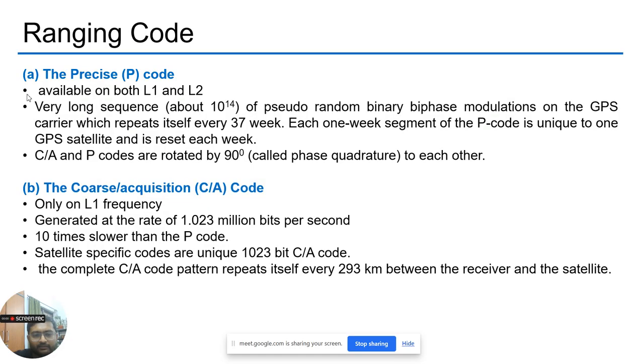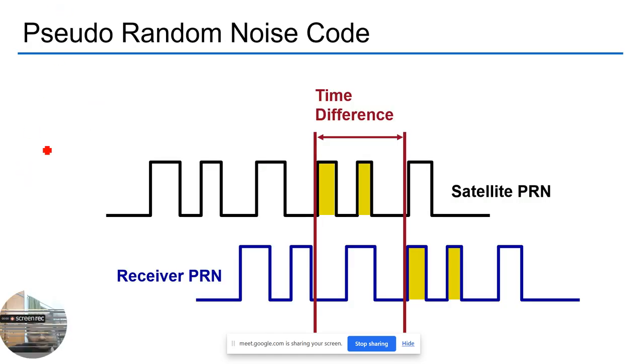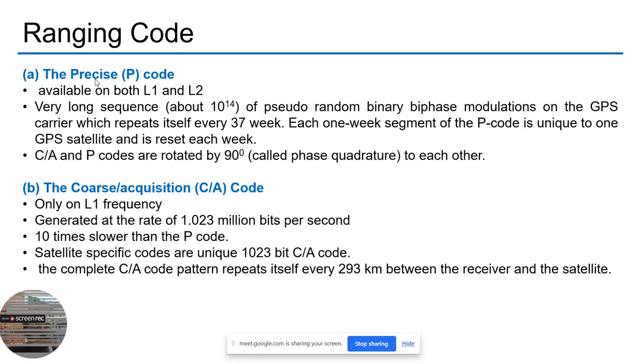And then, once we find which signal it is matching with, we take both the signals and find how much time delay there is, delta t. Once we get delta t, we multiply it with the speed of light and we get the distance. So basically it is just matching the PRN values, getting the proper signal, and then finding delta t. And this is more information about the P code and CA code which we use in GPS. Any questions?